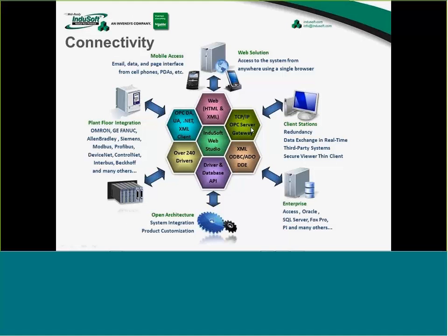We also have an OPC server as opposed to a client, where we might talk to somebody else's third-party server. We can be the server, and other clients can come and get information from our tags database. We can communicate through databases, really anything that's SQL-based, so we can get at Microsoft Access, Oracle, Microsoft SQL Server, MySQL, FoxPro, you name it. Lots of historians. Pi has an OSI historian, things of that nature.